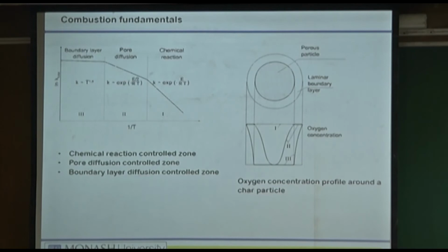That will give out the macro surface area, if I may say so, because the mercury molecule is very, very large. You can do the nitrogen surface area measurements or the CO2 surface area measurements. Nitrogen surface area measurements are done at room temperature, so the pores remain as pores. CO2 surface area measurements are done at cryogenic temperatures, and the pores can collapse. Sorry, the other way around.